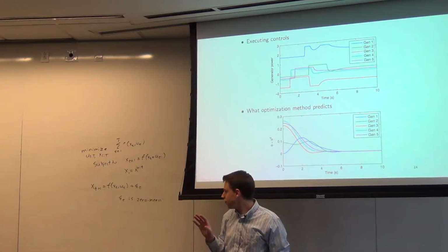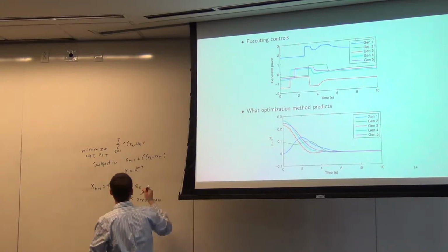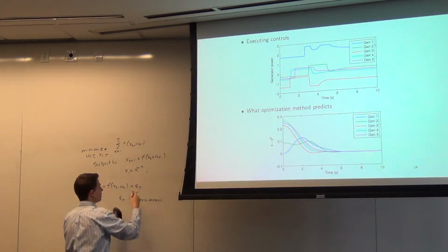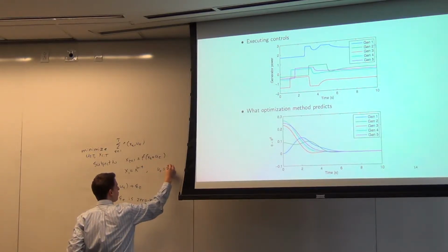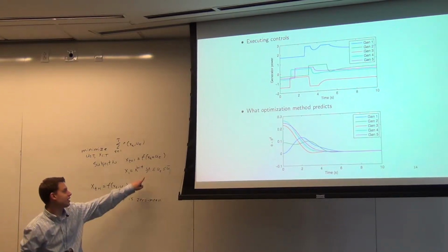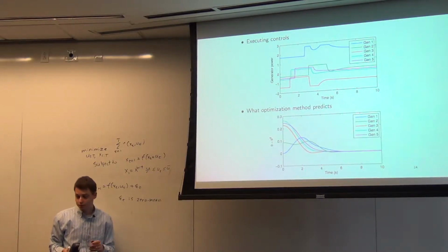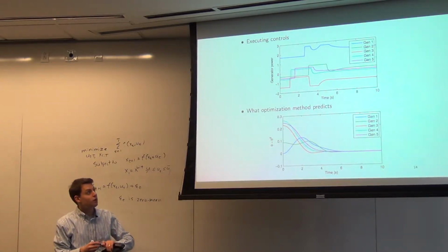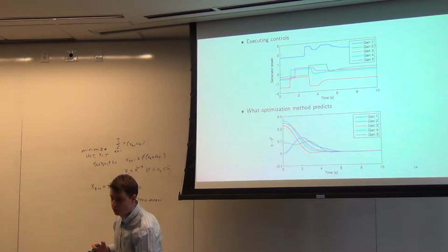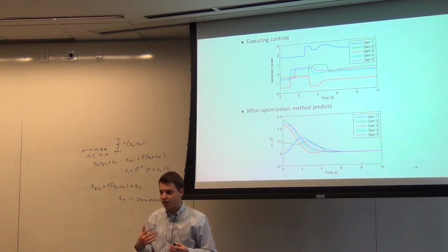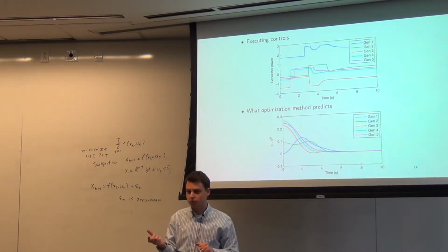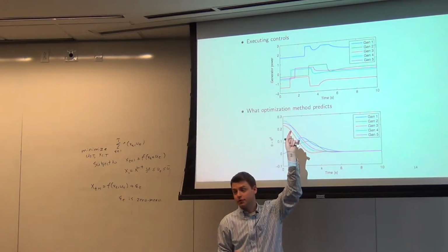And so remember, our benefit here was that when this is linear, say for example, we still can do things like have bounds, say on the controls. So say ut is less than or equal to some upper bound on u. Maybe I'll make these not time dependent. So we have some extra constraint like all our controls have to be bounded within some amount. And in fact, in this example, remember what we did was we bounded the generation of each generator we're controlling to be plus or minus 0.5 PUs above or below its nominal power generation. So that's how we get this pattern like this, remember.